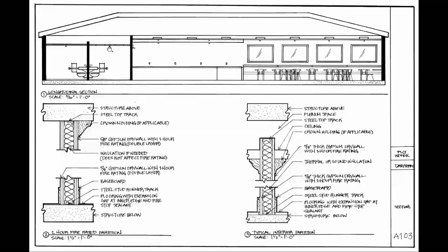This little object right here is a sprinkler coming down. And again, all of the ceiling things we're going to get into in a little bit more detail later on when we look at a reflected ceiling plan. But for right now, all you need to know is when we cut through the ceiling, this is an 8-foot ceiling, we see the actual ceiling thickness, so for lack of a better term, the drywall. And then we also are seeing where we would be cutting through the exhaust vent and the supply and return vents here. So that's what this is, and this is back here. There's a recessed can light right here, and like I said, the sprinklers here.